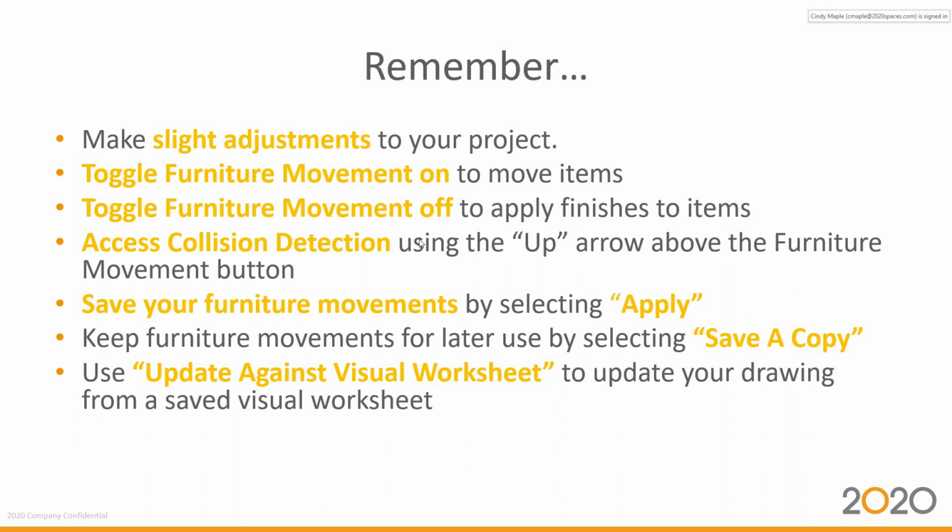Keep furniture movements for later by selecting Save Copy. Save Copy creates a separate visual worksheet that can later be applied to your drawing. Use Update Against Visual Worksheet to update your drawing from a previously saved visual worksheet.